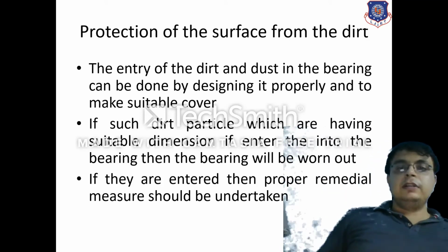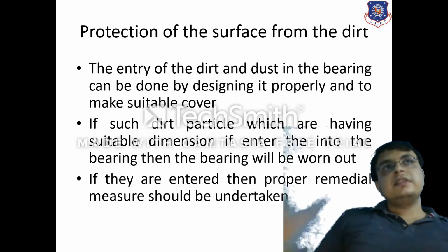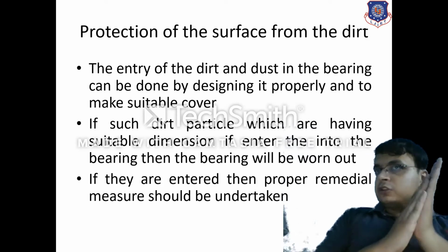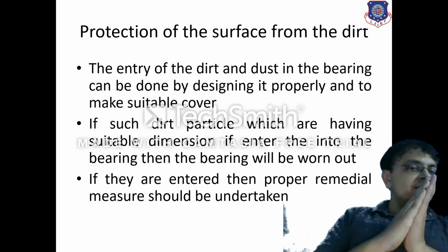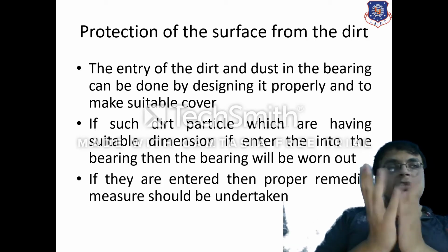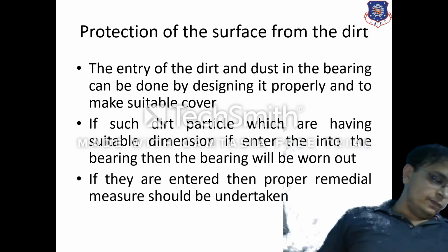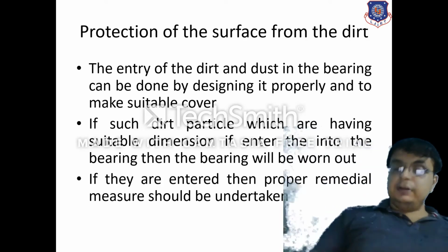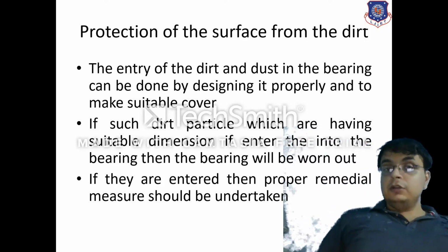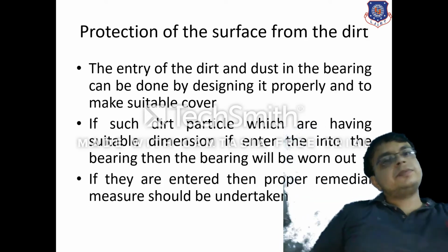Dust particles have some dimensions, and if they enter in between the two surfaces, then definitely an impression will be caused on both surfaces. The inner surface will get rough, and as a result, wearing will take place, and wearing out can also take place. So a proper remedial method should be undertaken to prevent the entry of dirt and dust particles from the atmosphere into the machine.